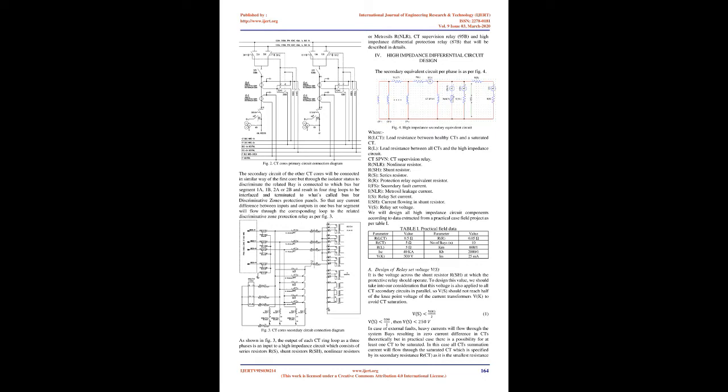The recommended classes for high impedance relays as per IEC standard IEC 60044-6 Annex D are Class TPS and Class TPX as they have low leakage flux properties.